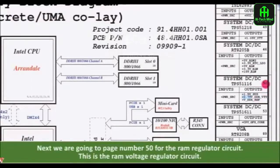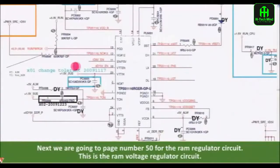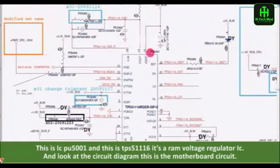Next we are going to page number 50 for the RAM regulator circuit. This is the RAM voltage regulator circuit. This is IC PU 5001 and this is TPS 5116, the RAM regulator voltage IC.